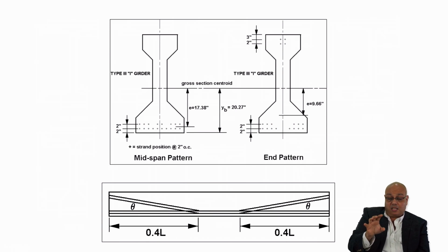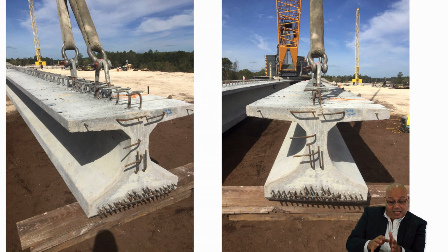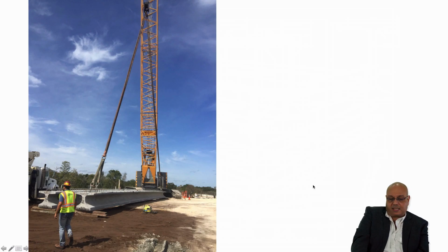And by the way, the picture that you're seeing here is the output of the LEAP software, ConSpan. In reality, the girder, or the FIB rather, looks like that. It's a prestressed concrete girder that can span 100 to 120 feet long, and as you can see here, it will be working perfectly well, and you can have these prestressing strands at the very bottom on the tension side, so it will sustain the huge moment that you're having.